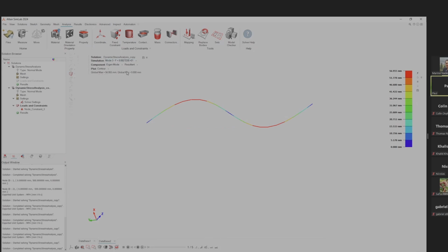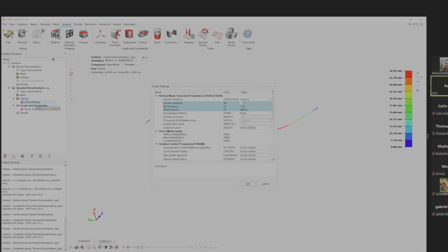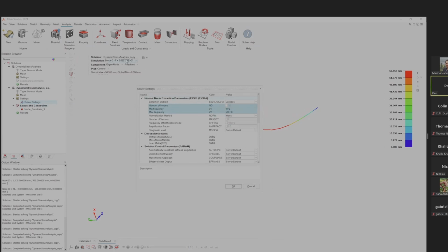We went over it in class. I didn't really give it the name first and second order, but pretty much. So in this case, it looks like what you'd want to do is click those solution settings, or solver settings, I guess we call them, and then change it from 1 to 500 or something. And it looks like this gave me about 8 modes. So if you wanted to increase this slightly, you can.